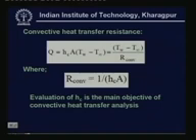Now, similar to conductive and radiative heat transfer, you can also write the convective heat transfer rate in terms of the temperature potential and the resistance. So, you can write Q as Tw minus T infinity divided by R convection, where R convection is the heat transfer resistance to convection. And if you compare this equation, you can easily show that R convection is nothing but 1 by Hc into A.